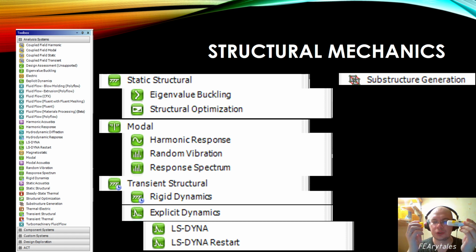And we can solve it separately. Additionally, we can use static structural for submodeling. We can solve this one with a coarse mesh and then use the result of the coarse mesh for detailed modeling of this part of this cup, for example. And submodeling and substructuring are a very good and very important way to solve our tasks. They have their own benefits and problems.